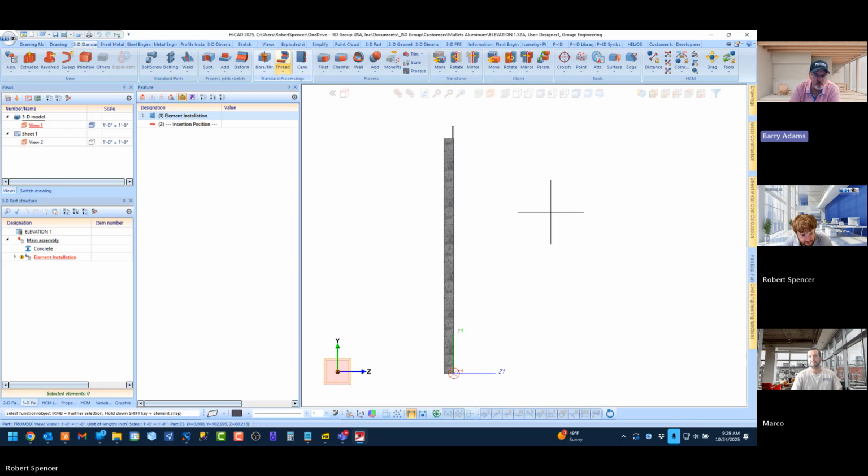Well, there's a lot of imperfections on the walls. They'll have peaks and valleys, and we'll try to work off the peaks and add shims for the valleys. So, very similar.